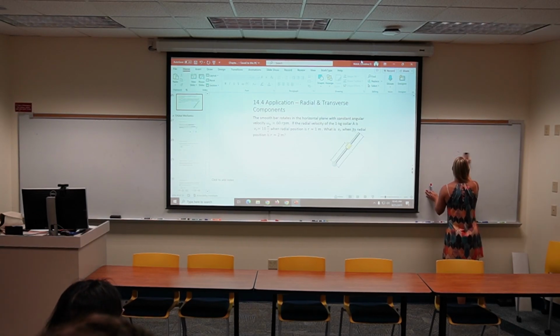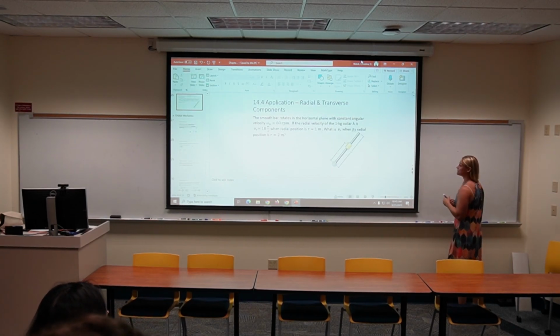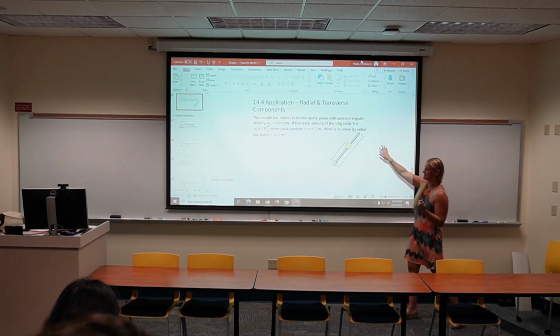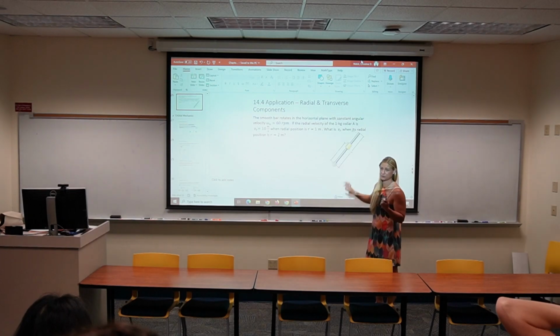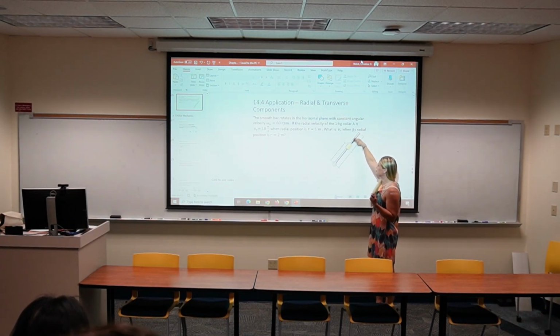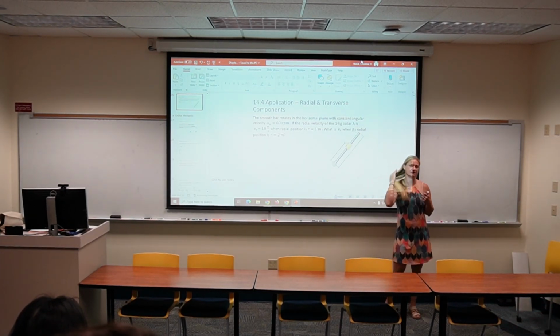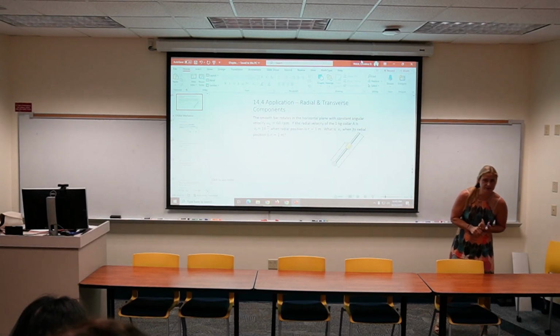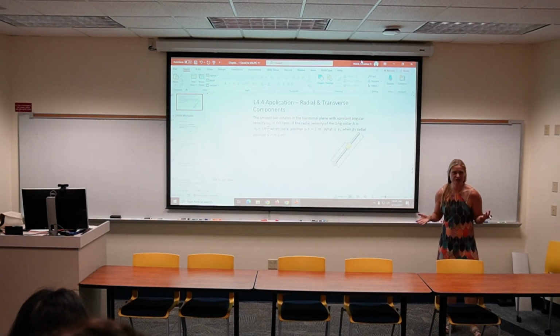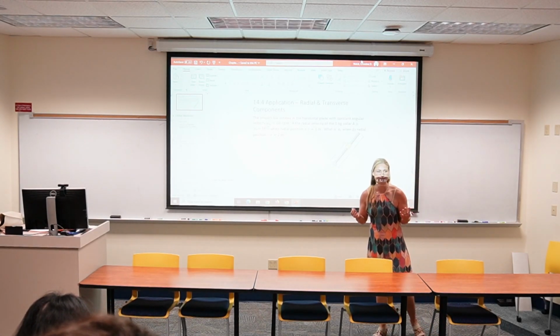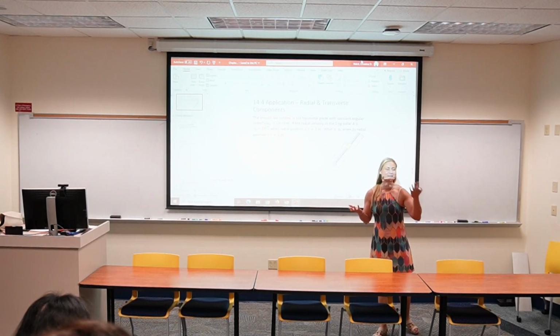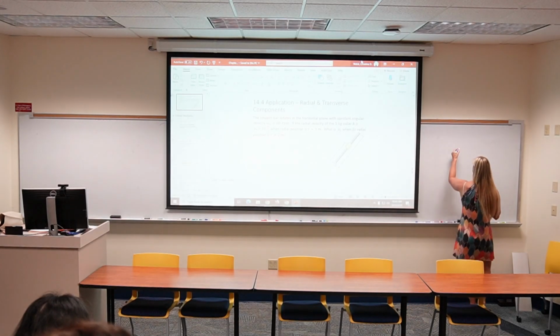What is the difference between, first of all, is there any difference? This is the exact same question, literally, with the same values and everything, except you have a spring attached here. So it's pushing on this guy. Yeah, it's pushing on the sleeve. Is your four-step process going to change? No. Did acceleration change as a function of position? No, it's all the same thing. What is the one difference? You have to have the spring force in the free body diagram. That's it. Very good.